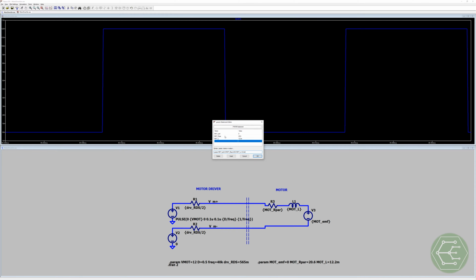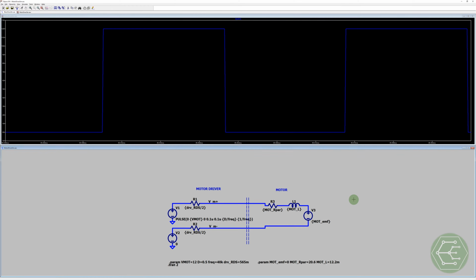And then it uses them in an appropriate situation. This is great because if we want to model our EMF as a function of speed, we can put that equation into SPICE, and then you can put RPM as a variable, and that gets used, so you can do the hard work once, set up all of your equations, and end up with a reasonable model.